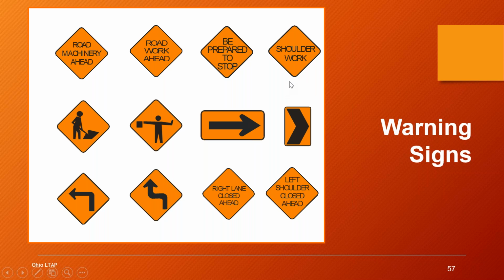On a multi-lane roadway in the peak hours, we need every lane available to traffic. So if you're out there working between 7 and 9 a.m. or close to the PM rush hour and you're not blocking a lane of traffic, we really want you to set up your work zone with a shoulder work sign, and that would be typical application number 4 or number 6.